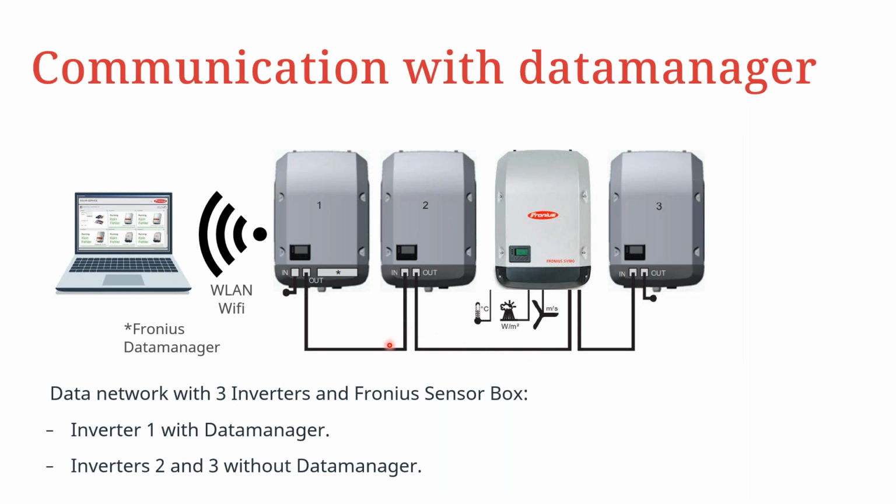Once this is done, you can have seamless access to the system with your monitoring device. So basically, if, for example, as you can see in this case, you have the Fronius Sensor Card installed inside this inverter, if there's any query or inquiry for data, it will have to go through the data manager, that is through inverter 1, and then the inquiry is made for the sensor or whatever parameter is being requested. This information is then fed back through the data manager to your monitoring device. So that's basically how the communication goes.